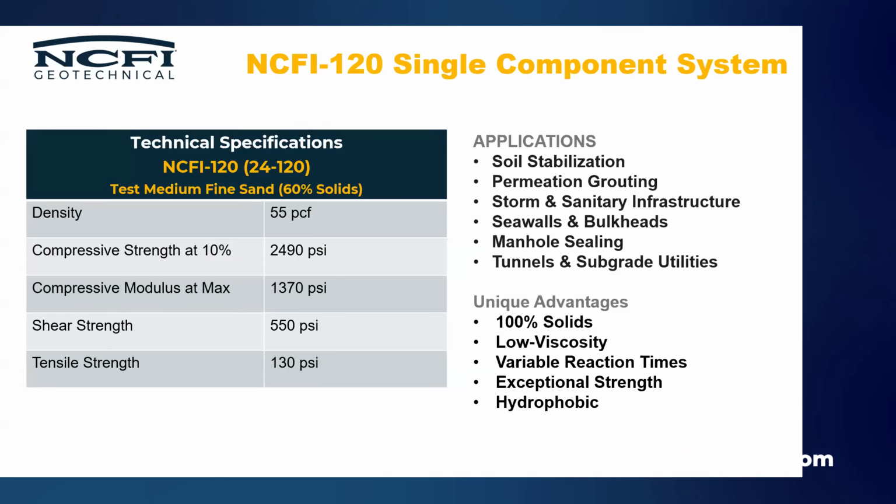Single component is a little bit different, and it's typically going to either be run through, say, a paint pump, or sometimes even out of cartridges. Single component does sometimes have a catalyst package that can be added. Everybody says, well, then is it really single component? It is. The catalyst package is basically your ability to adjust that product in the field. It's adding catalyst to it to speed up the process. It's not what makes it react. It's just speeding up the system. So it's just the ability to adjust that system in the field by adding some catalyst to it.